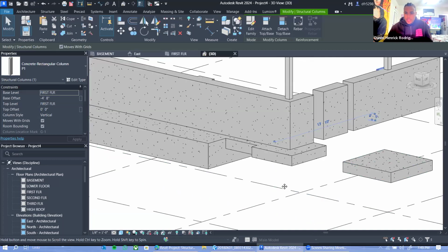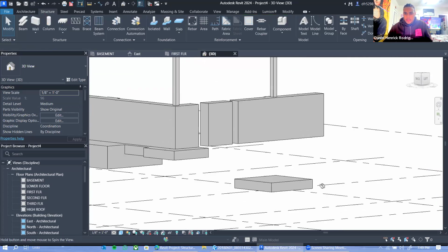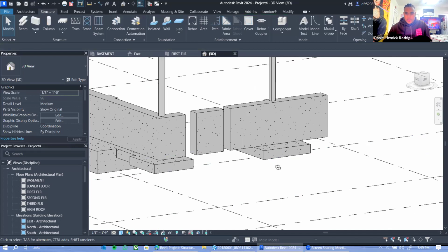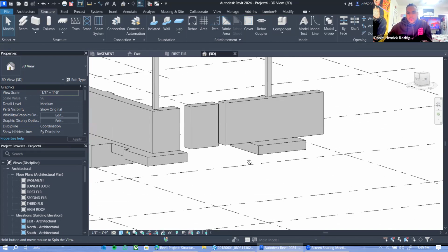And if we look at it in 3D, it will check out. See that? Right there. And our pier right here doesn't connect it. It's also -9, so I'm gonna make it -4.8. There we go. Now the wall is actually sitting on it. Beautiful. Having 3D open and doing these quick checks is always helpful to you guys.